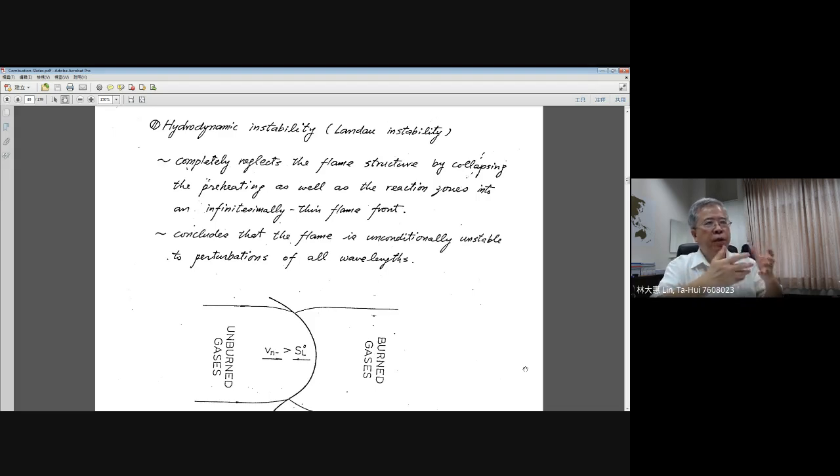For example, we introduced the flat flame propagating in stagnation point flow or counterflow, or as we say, impinging jet flow. And we used the Bunsen flame to let you know the influence coming from flow stretch coupled with the Lewis number.